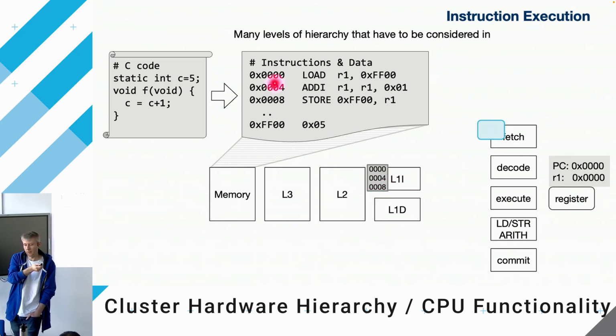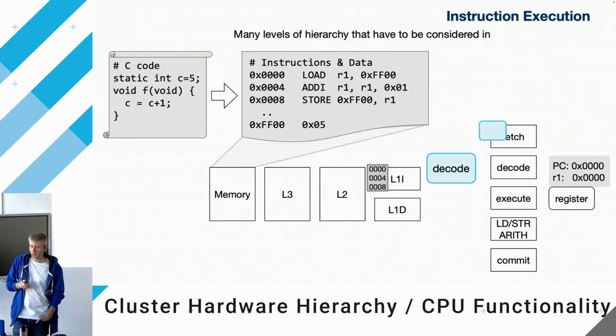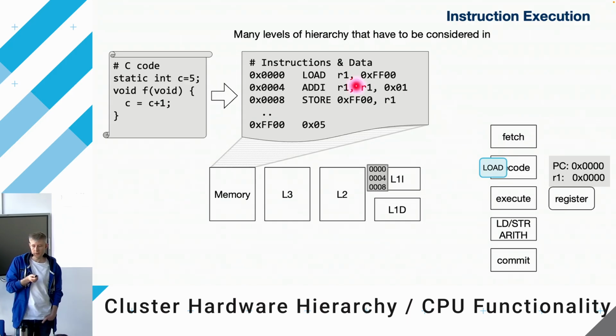And we see here the addresses correspond to our program binary. So the instruction was fetched, and now it's inside of our CPU core. And the next step is the decode step. Therefore, the CPU has to understand what kind of instruction it is and what the arguments are. So we see here it's a load instruction, because the first thing to execute this line is to load the data stored in the C variable.